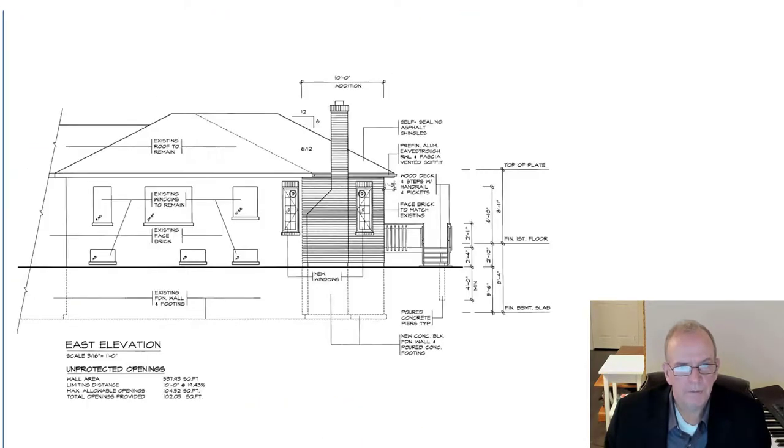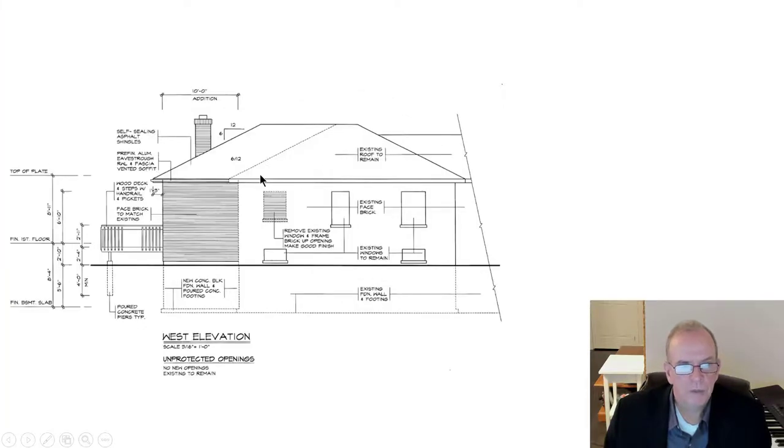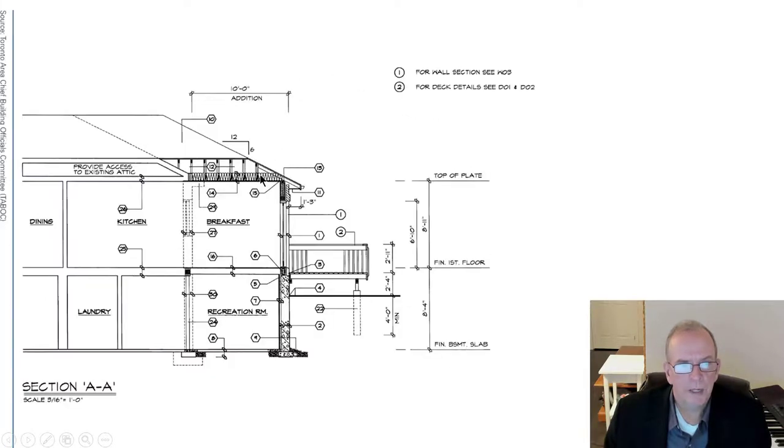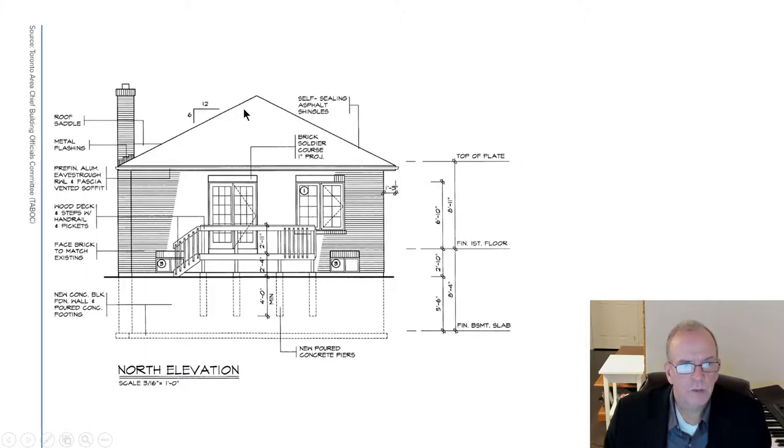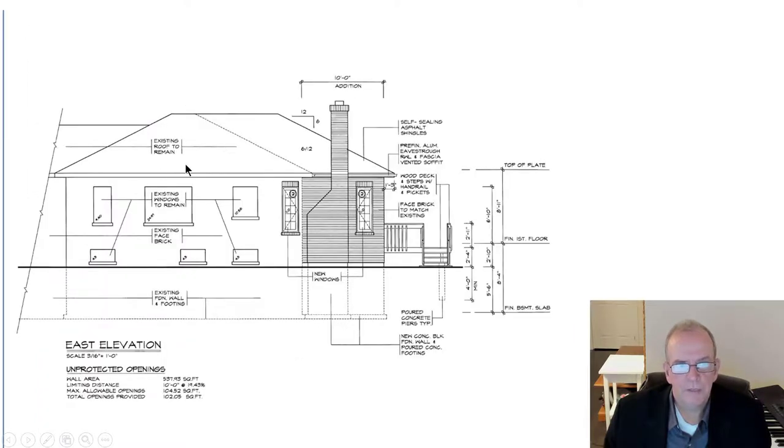There were another couple of things that I wanted to bring up. Well, tying into the existing roof. So it's a 6/12 slope, 6/12, so no matter where, the back house is 6/12, so it's an equal slope roof. I'm not building this thing 6/12. I'm building this thing to whatever this existing roof is. So maybe the consultant did it and it's 6/12, but you know what? Maybe it's sagged and it's not 6/12. Maybe it's actually 5.5/12.